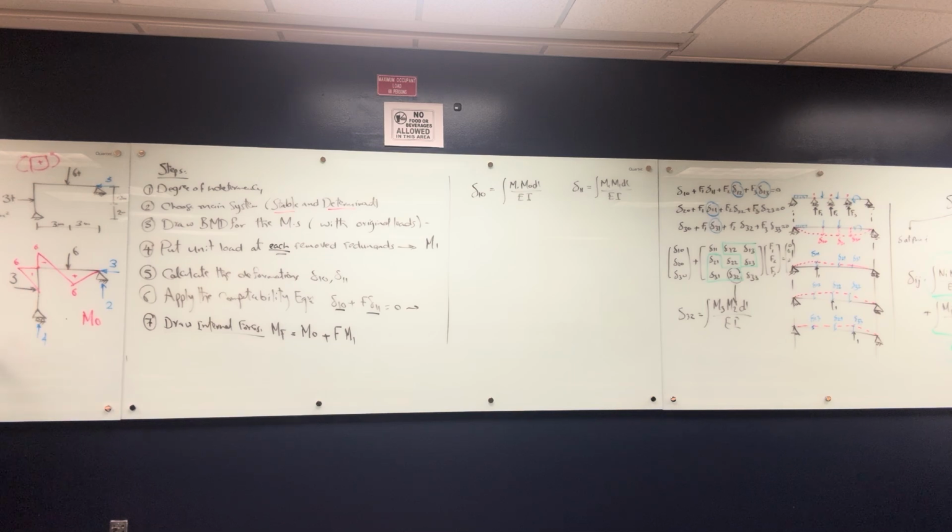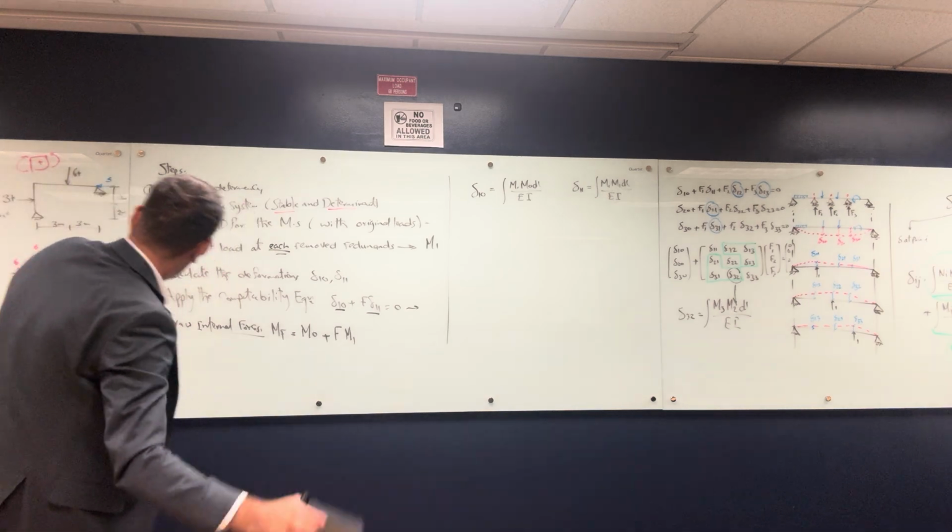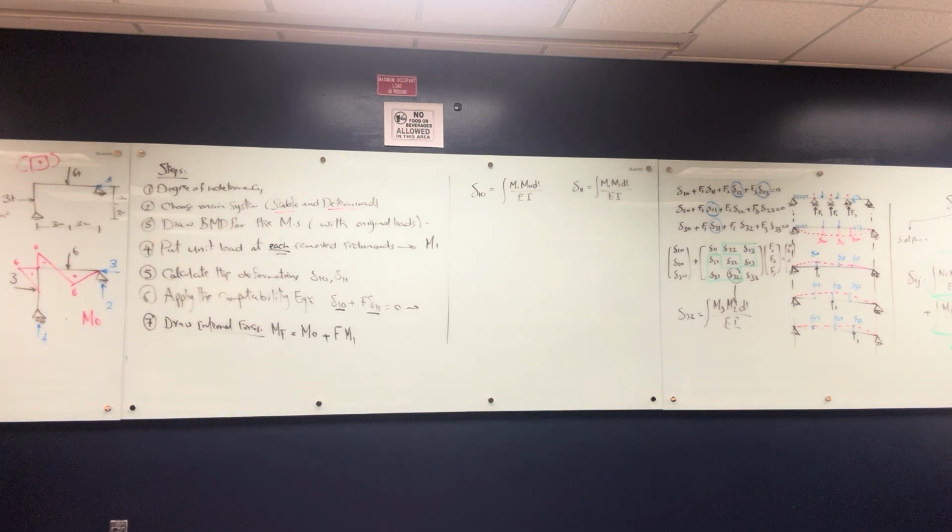By the way, this is in centimeters, so let's keep them in centimeters. So I'm going to put 20 multiplied by 40 cubed over 12. It's going to give me a number with a lot of zeros. 106,666.67. That's a hell of a number.